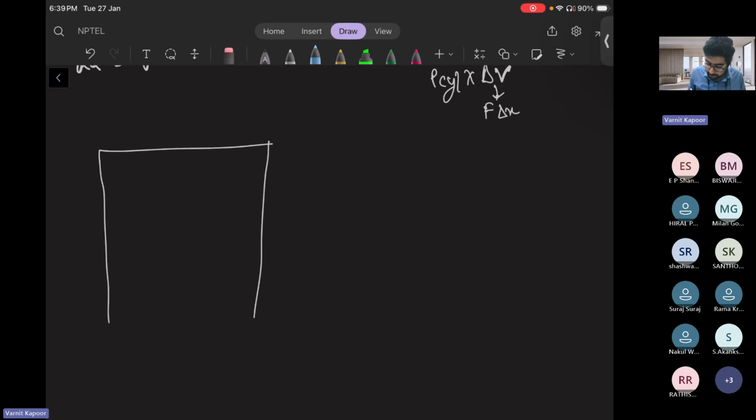Now your piston is here at this scenario currently, at BDC, bottom dead center, and this is your TDC, your spark plug. Then I have my inlet valve that will remain closed, but my exhaust valve will open at that instant itself.